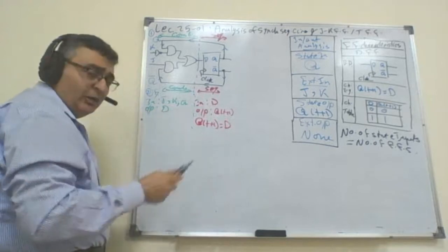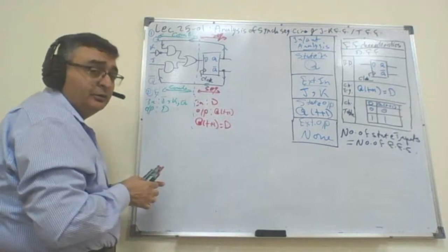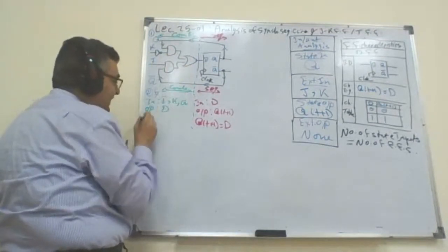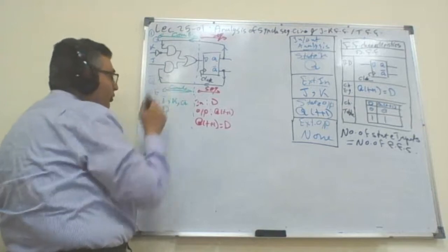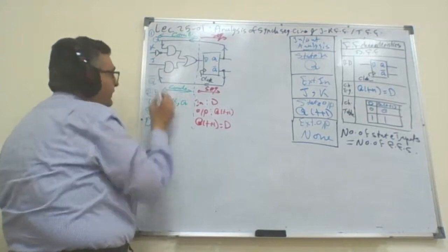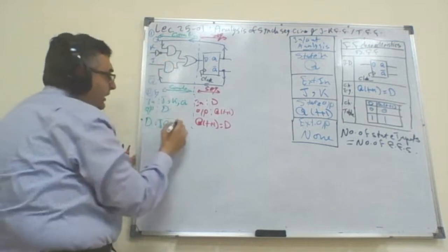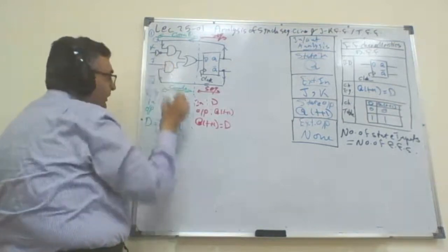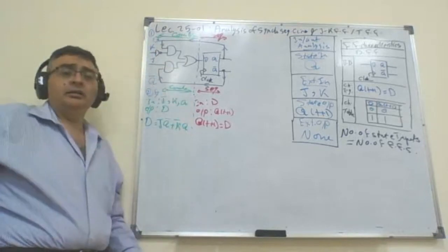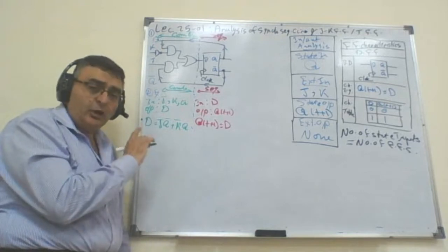Analysis for this, you are clever in that even from chapter 2. Okay, can I analyze this? Yes. I have here D as an output equals an AND-OR between two things. The first thing here is J ANDed with Q bar, ORed with K bar ANDed with Q. Done. Done deal.